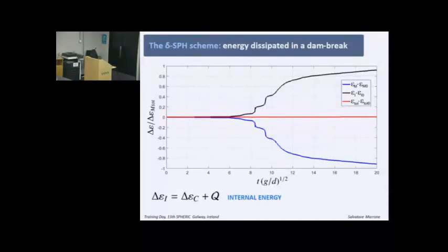And if it's true, it means that you are making few errors with your time integration. Because in the time integration, you can dissipate energy, you can make errors. So if the error that we commit in this total energy is large, it means that it's your time integrator that is making these errors. So this is a way to check also that your integration time step is good, and that you're making few errors in the time integration.